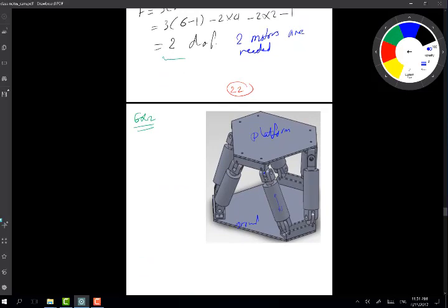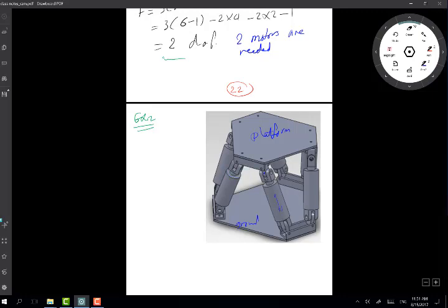Now, in this specific case, my question to you is whether I should allow the pistons to rotate inside the cylinders, or just lock up this rotational motion. If I lock up the rotational motion, I'm going to pay more money, by the way, for the design. But let's say I want to discuss this with you from the kinematic point of view more than anything. Right, so let's calculate the degrees of freedom if the pistons are not allowed to rotate. So that's case 1.